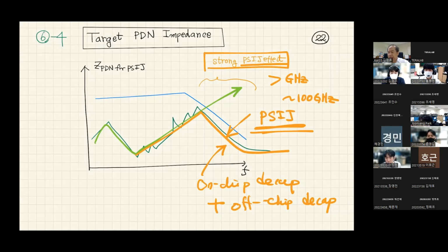So far I was talking about the overall picture of the design of decoupling capacitors at PCB level and package level and on-chip level. And I wanted to give you several different strategies: hierarchical design, frequency dependent, position dependent, multiple design, and on-chip resonances.